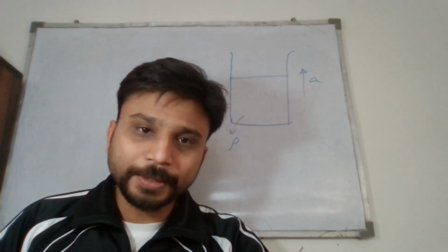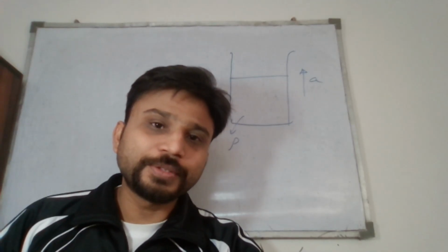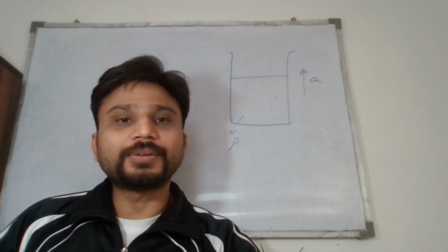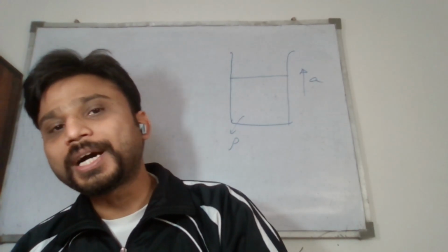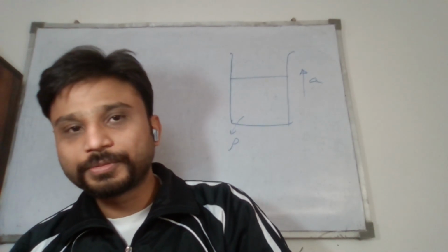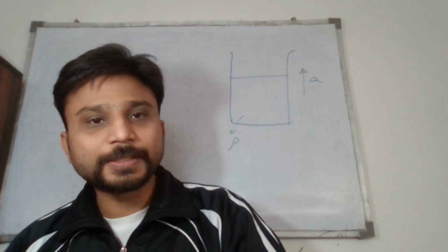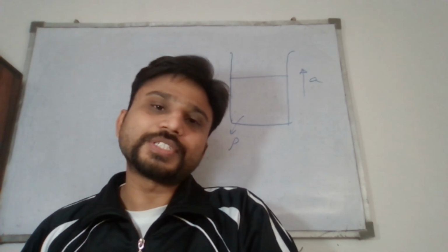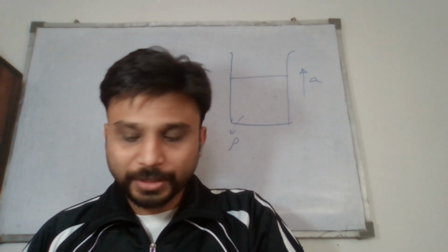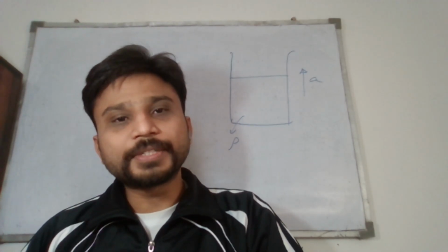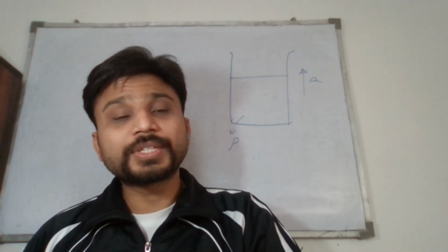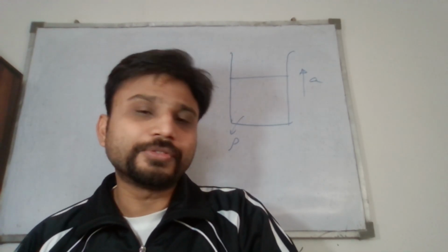So we can rotate it. In case of rotation, we already know that the particles which are of higher density get thrown to higher distances from the axis, and the particles which are of lower density remain close to the axis. So this is one of the principles which we can use. In those cases, how do we calculate the pressure difference?